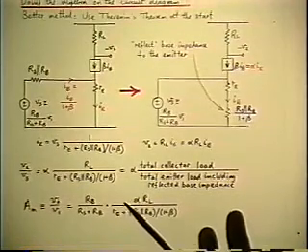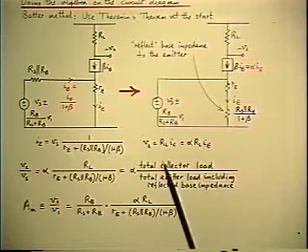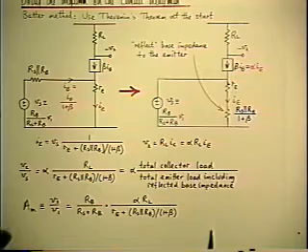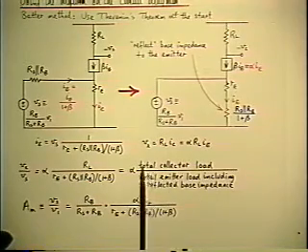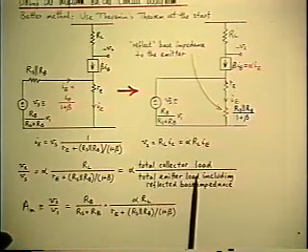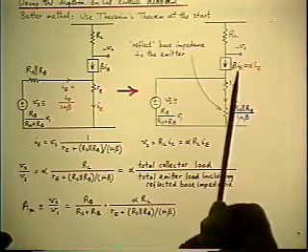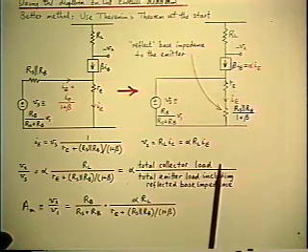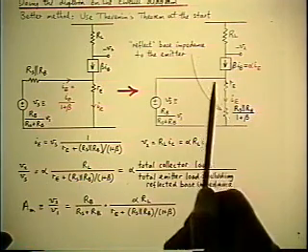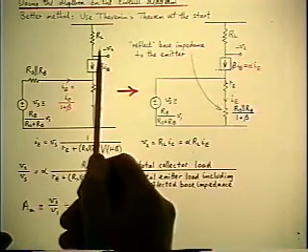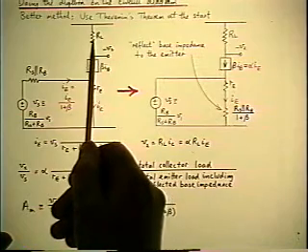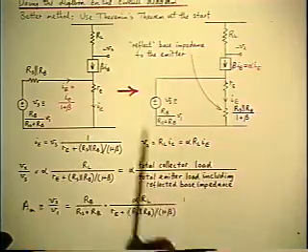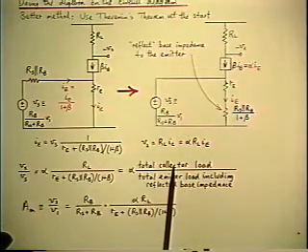And notice that having done it this way, you never have to do this again for any other common emitter amplifier stage if you simply remember this result in words. The voltage gain of the basic common emitter amplifier stage is the total collector load, which is a generalization of the RL, because obviously whatever network there may be up here, it's just the total impedance that multiplies this current generator to give you the V2.